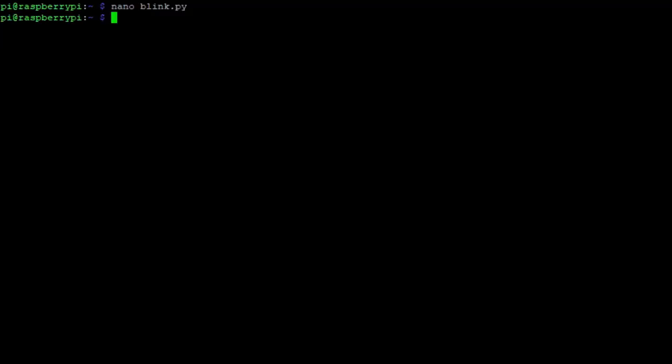I will not include unexport here because it makes the script a bit more difficult, but basically we can try to run this. We do python3 blink.py and there it prints. And this is the actual state of the GPIO right now. If you would take a voltage meter, you would see that it's just changing from 3.3 volts to 0 volts. And it is as simple as that.